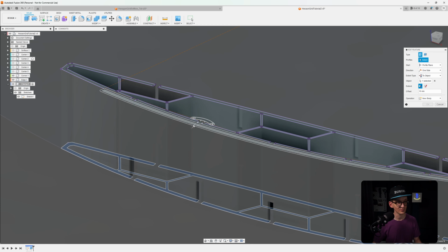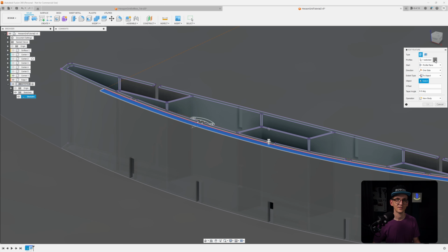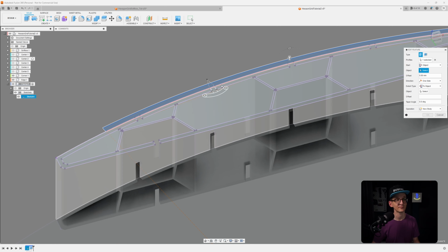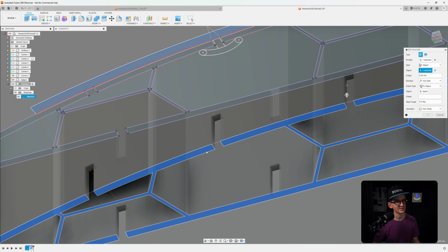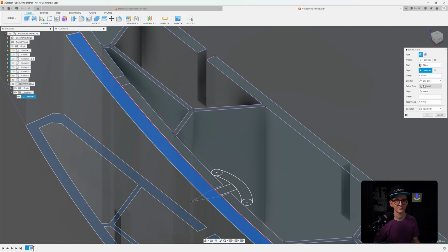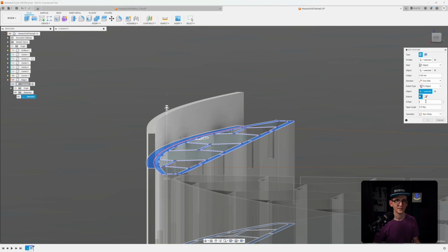So we can do that, although the shape is here. So we can do that by selecting a start point different from the sketch plane that we're currently sitting on, and selecting this side. And now we can go and extend it all the way to the upper side. Yeah, to object, select this one. Now it's going to go all the way.